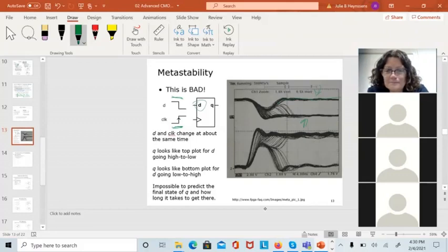There are other things you can see in here and this is called jitter. And you'll hear me use this expression frequently from now on. You can see that sometimes I get this clock edge here, or sometimes the output switches here. Sometimes it takes a little bit longer to switch.